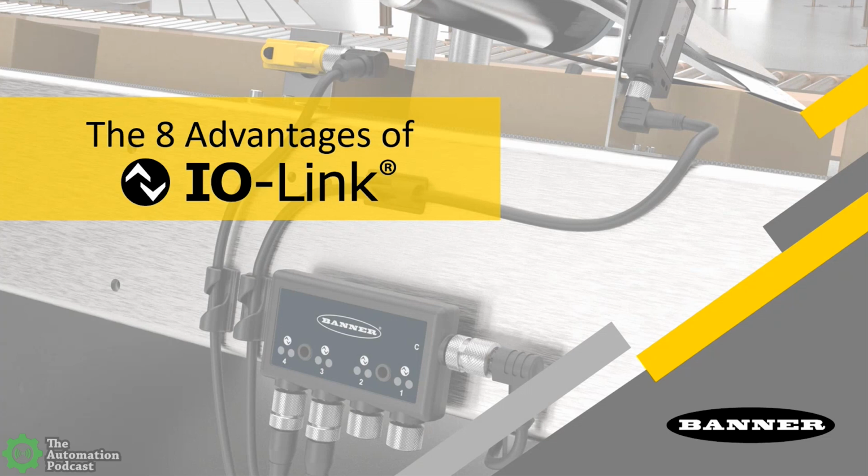That's one of the big drivers why people, especially OEMs, have started adopting IO-Link, because they're able to standardize on that nice M12 connectivity. Another thing before I move on is that you can run up to 20 meters between an IO-Link master and an IO-Link device. And the last piece before I move on is that IO-Link is not proprietary to one sensor manufacturer.